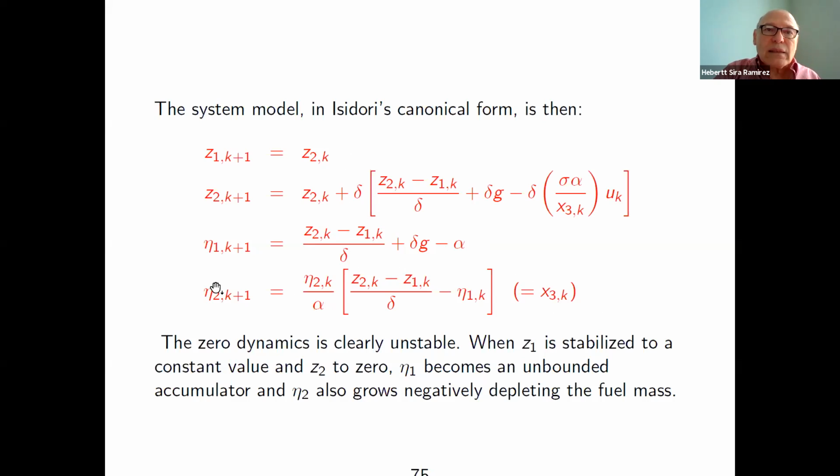The velocity of the gases determines very much the zero dynamics, and eta 1 is the value of the zero dynamics, which is constant. And that constant might be greater than 1, and you have an unstable zero dynamics. But in essence, the zero dynamics will bring you the behavior of the remaining dynamics when you have a hovering maneuver over that planet and your height has been stabilized at a constant value.